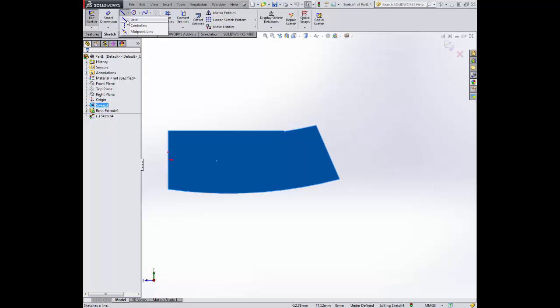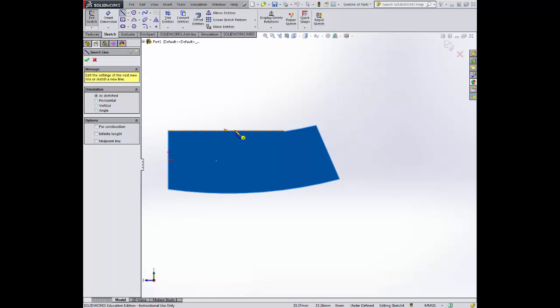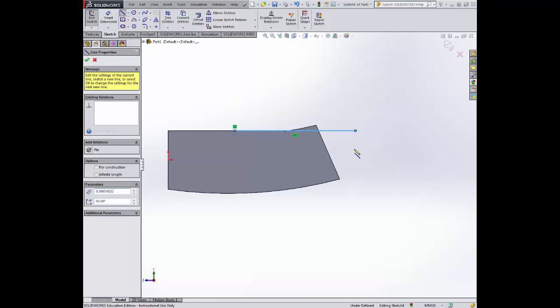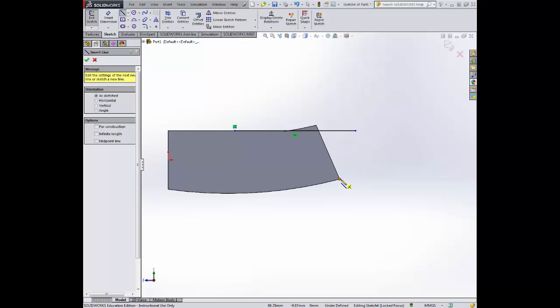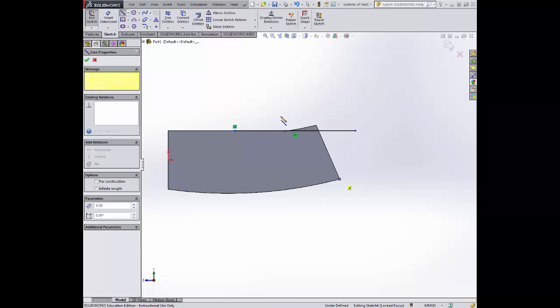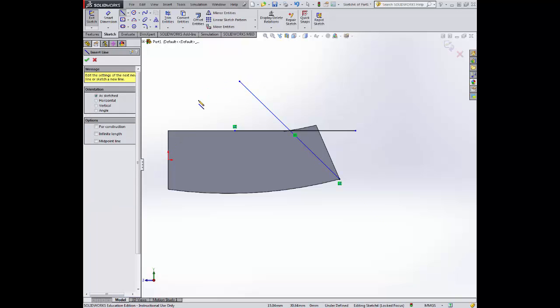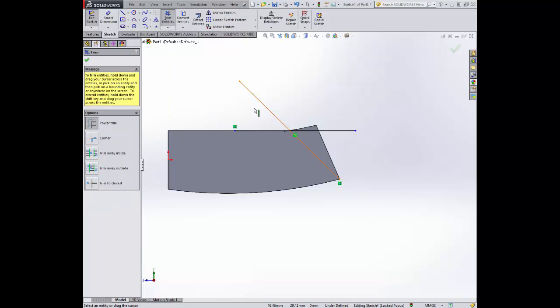Again, using our line tool, we're then going to give ourselves some key lines. What I'm doing is I'm following the lines that we've already got. I'm going from this bottom corner here. And I'm going to find this until we get our 45-degree angle. Now, this doesn't always pop up. As you can see, it's popping up there. Yes, it will try and snap to other things around it, so be careful on that one.